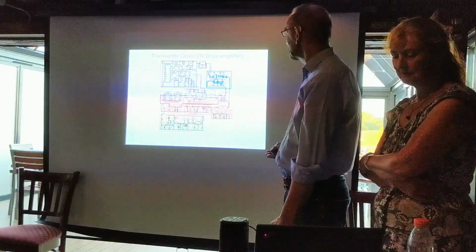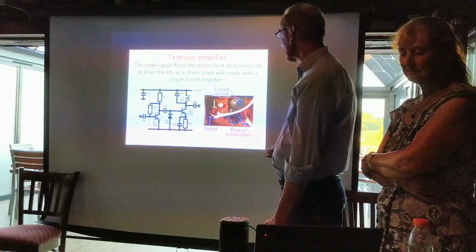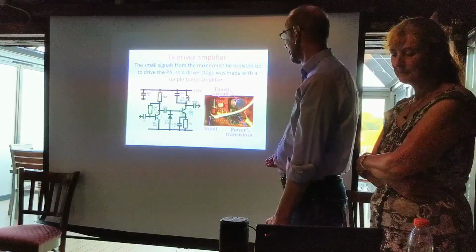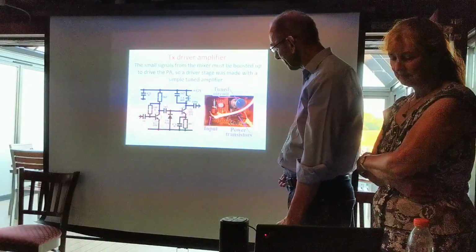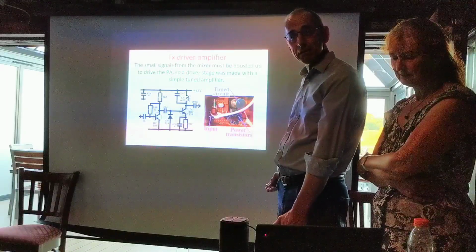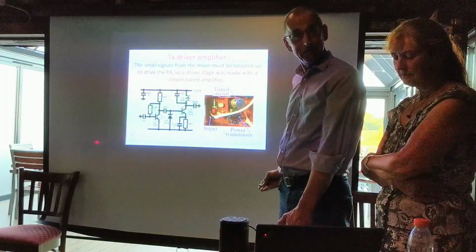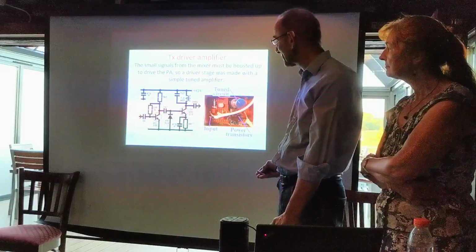Okay, the transmit drive amplifier. So you've got very small signals coming out of the mixer, and you need to boost those up to drive the power amplifier. So basically what we've got here is a pre-amplifier stage, which actually I pinched from a hi-fi I made millions of years ago, hence the BC109. The BC109 works up to 600 megahertz, so it's fine at 472.